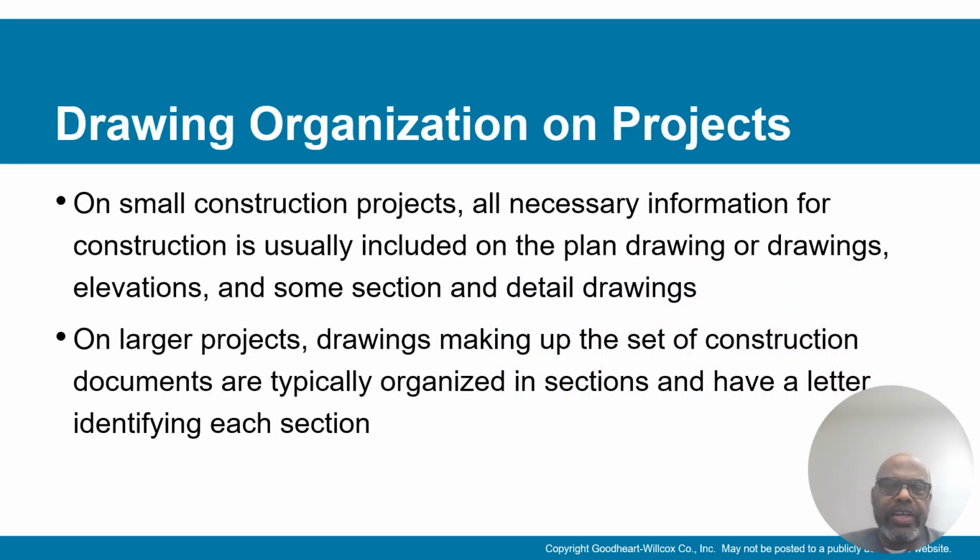So during organization on projects, when it comes to small construction projects, and like I say, small, they're just remodeling a room, it might just be all on one page. However, on very large projects, it would be multiple pages of content. And it would be so large that it may have different sections for the different trades. So, therefore, the carpenters, the electricians, the HVAC will all have their own section in the drawing.